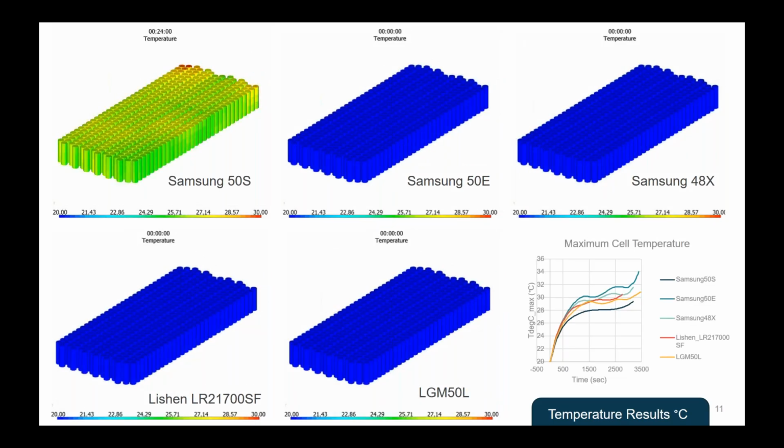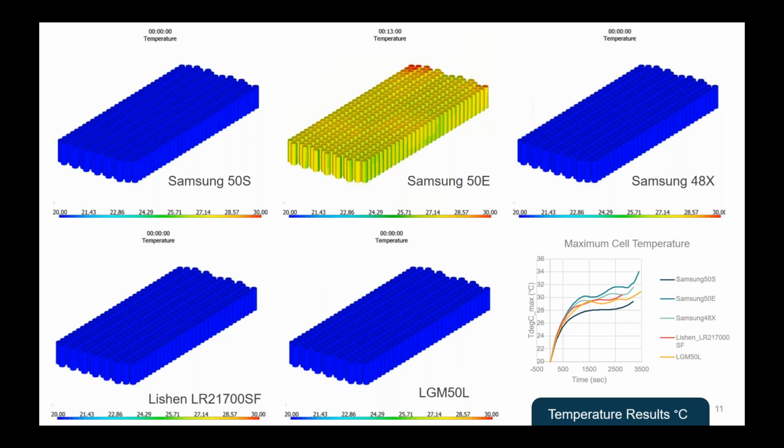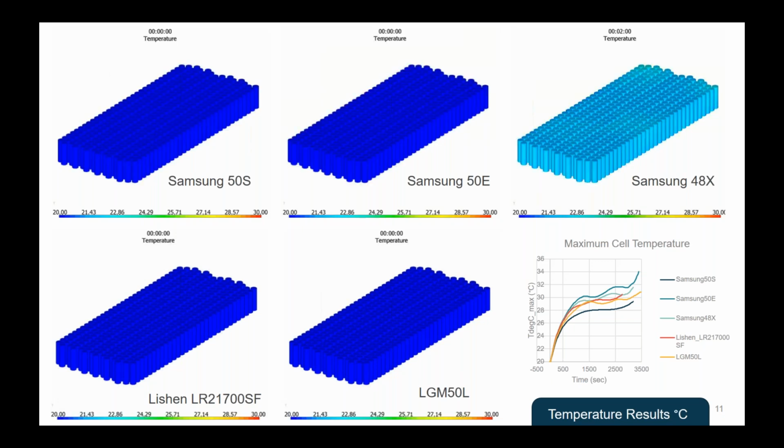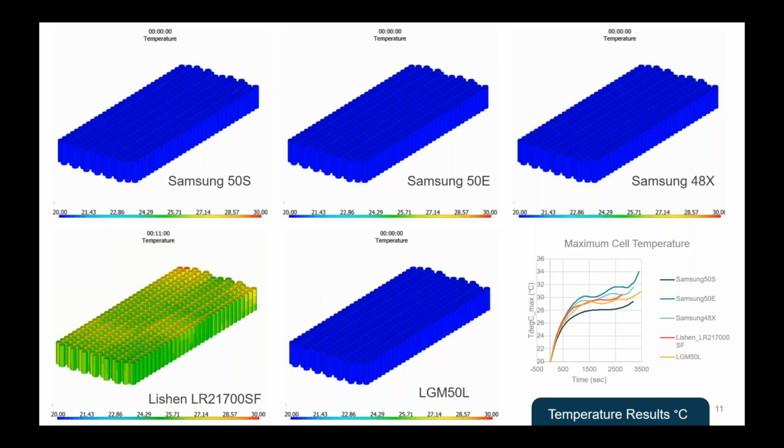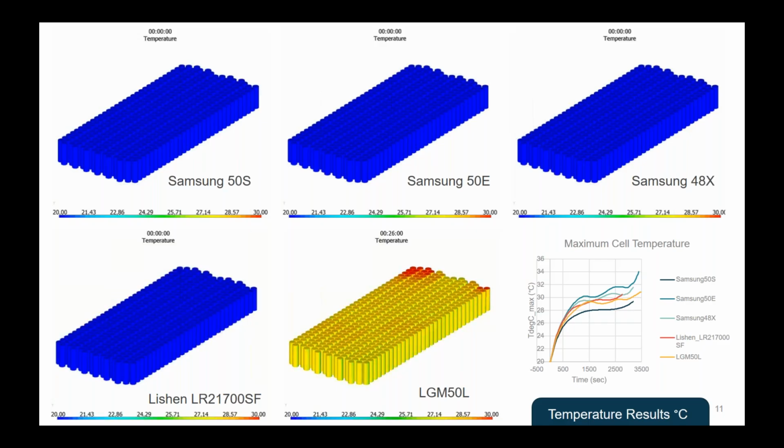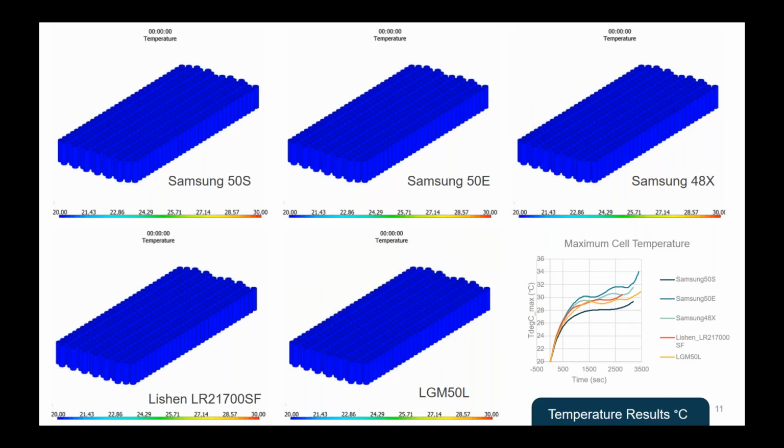If we look at the cell temperatures, we can see the influence of those heating factors and cooling factors on the cell temperatures compared for the different cells in the pack. So some cells are getting warmer due to the Joule heating of the bus bars connected to the cells on top and bottom, and some cells are getting warmer from the heat up of the fluid stream as it flows through the pack.